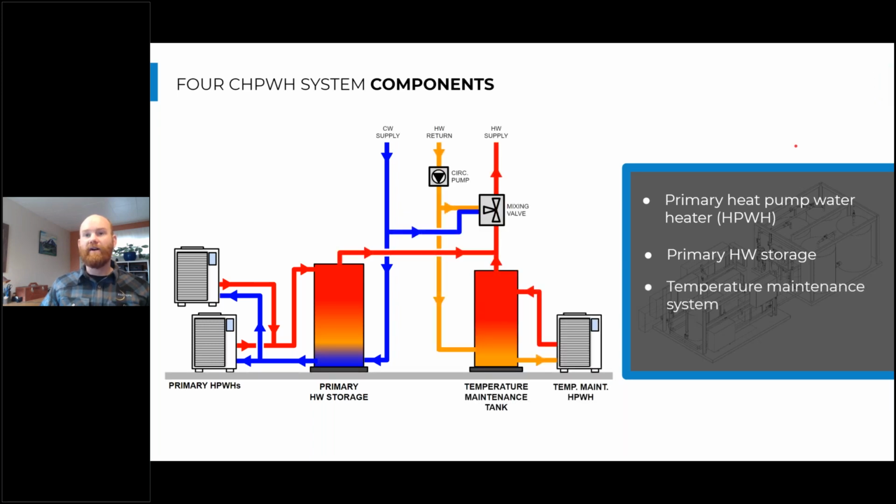We also have a temperature maintenance system. And we have a temperature maintenance system in a gas water heating system as well as an electric resistance water heating system, but it might be the same as our primary heat pump water heating system. For commercial heat pump water heaters, depending on what technology you're using, you might want to separate that primary system from your temperature maintenance system. And so I'm breaking those two systems out here.